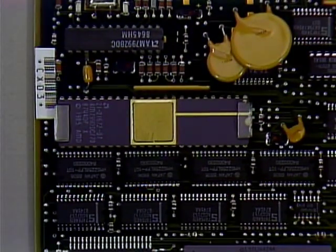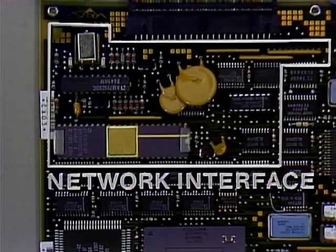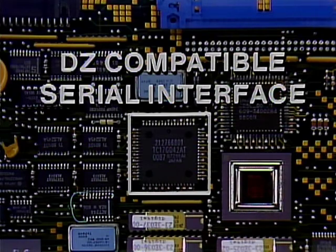The network interface supports either standard or thin-wire Ethernet. It has a network data buffer because of latency constraints. This is a DZ-compatible serial interface. There are 4 asynchronous lines available for use by a keyboard, mouse or tablet, modem, and a printer or auxiliary console.